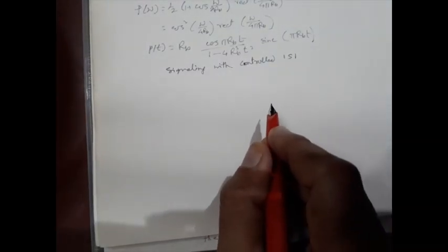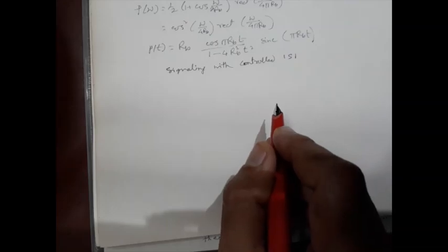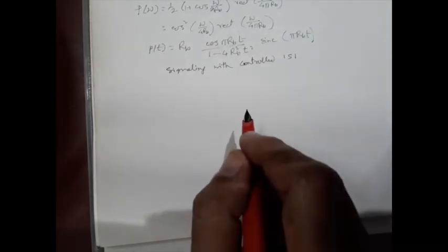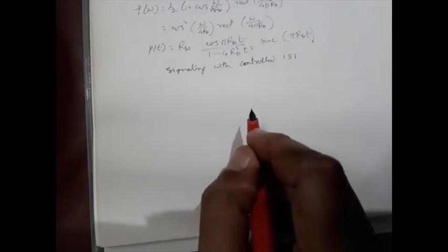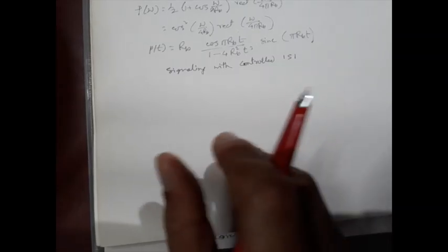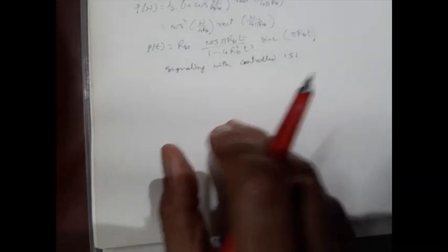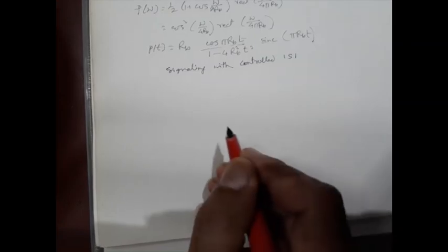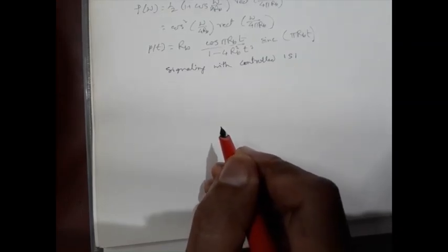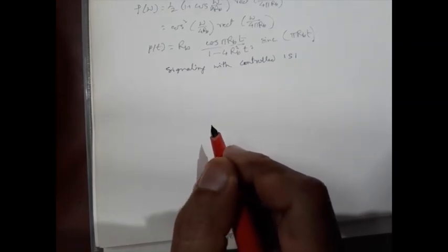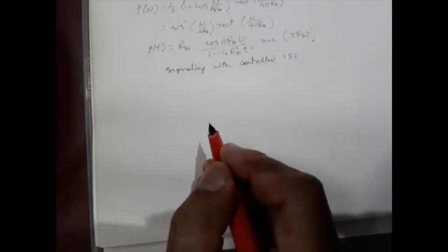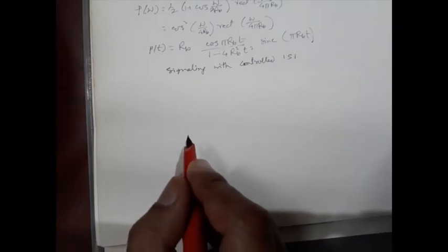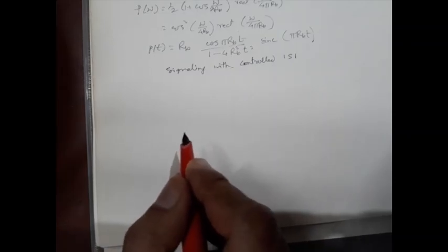The Nyquist criterion pulse results in a bandwidth somewhat larger than the theoretical minimum that we have seen. If we wish to reduce the pulse bandwidth further, we must widen the pulse. So widening the pulse may result in interference with the neighboring pulses, right? However, in the binary case, with just two symbols, a known amount of ISI may be permissible because there are only a few possible interference patterns.